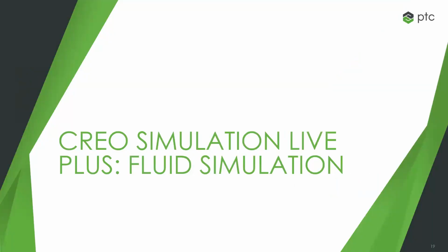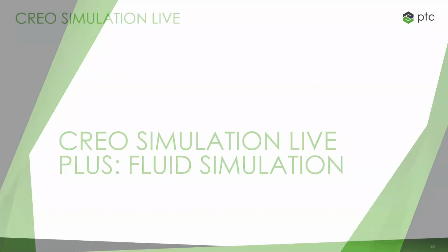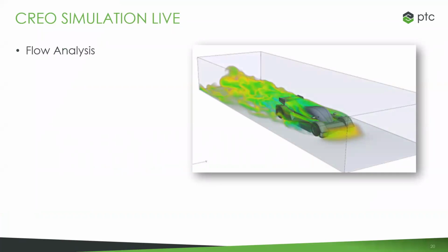And that's really the first place where I want to start here. So this is something that we've had with Creo for quite a while now. I think since the release of Creo 5, we introduced Creo Simulation Live. And if that's something you haven't heard of before, I just want to give a bit of background into it. It's essentially taking what you would normally have with your simulation, where typically you have to build out a mesh and you have to do defeaturing and all of that. Well, with Creo Simulation Live, you don't need to do any of that. It's just something you can run instantaneously. You get results back immediately, and you can do that for structural, thermal, modal simulation.